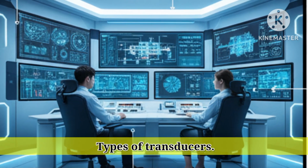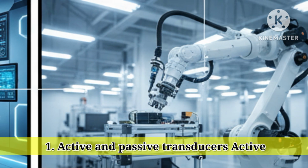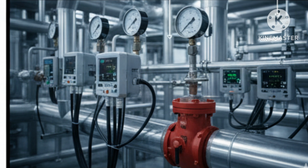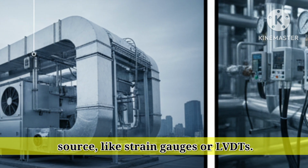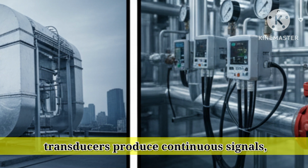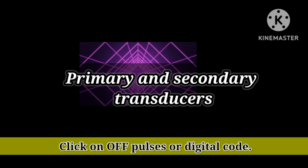5. Types of transducers. Now, let's talk about types of transducers. We can classify them in several ways. 1. Active and passive transducers. Active transducers generate their own electrical signal, like thermocouples or piezoelectric devices. Passive transducers need an external power source, like strain gauges or LVDTs. 2. Analog and digital transducers. Analog transducers produce continuous signals, like 4 to 20 mA output. Digital transducers produce discrete signals, like on/off pulses or digital code.